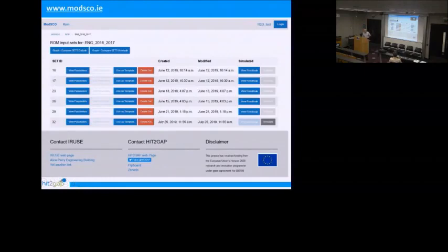Maybe this model contains a certain set point, and this one contains another schedule for occupancy, or maybe another schedule for winter and summer availability of systems. So all of these models are run. A first model is run also and calibrated. We did 3 models and calibrated against real data for 2015 on this building, and then compared with the results of the model. Okay.